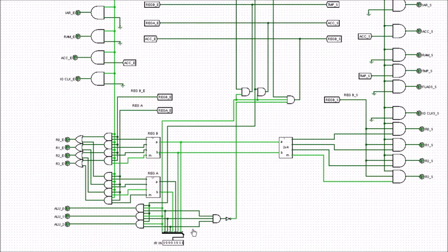So similarly, we can look at these two bits here, and you can see that this is them heading up there, and there's a 1 and a 0, and this goes into our Reg A. Again it's a 2x4 decoder, so it takes the two inputs and gives us our 4 possible outputs. And you can see here we're actually choosing 1, 0, which is number 2, so that goes to register 0, 1 and 2.